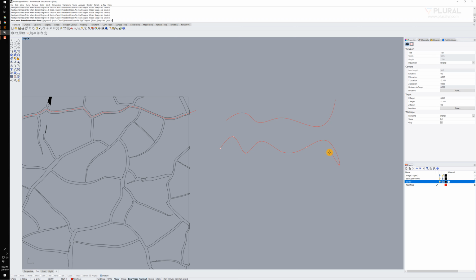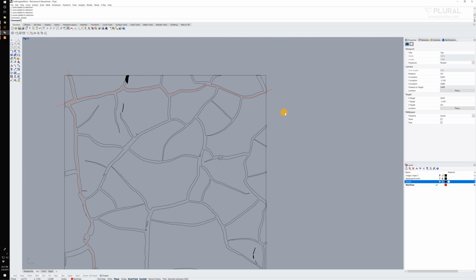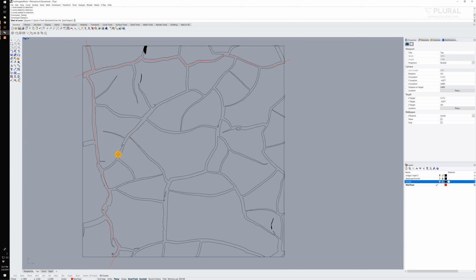Sometimes you can see I really have to get in there and put a lot of control points if I really want to control the curve. But there's a huge difference between a curve using this, which is a Bezier curve, and an interpolated curve. While they still have these control points that look very similar, this one's generated by me clicking the actual lines the curve moves through. I'll click both of these and hit delete, and we'll come back in with an interpolated curve and do some of the line work in here.